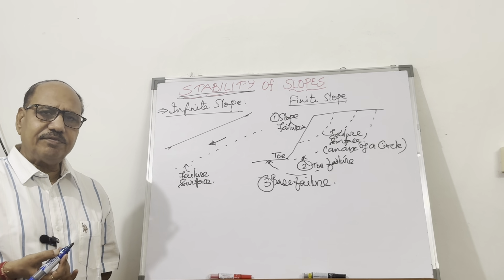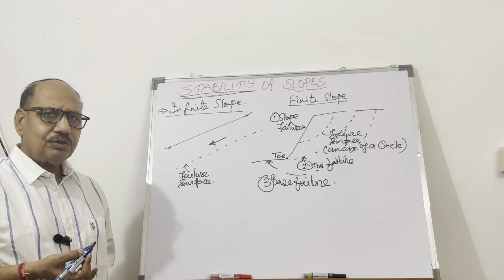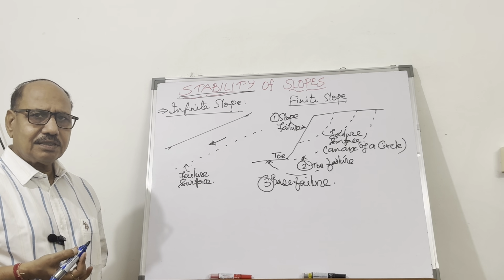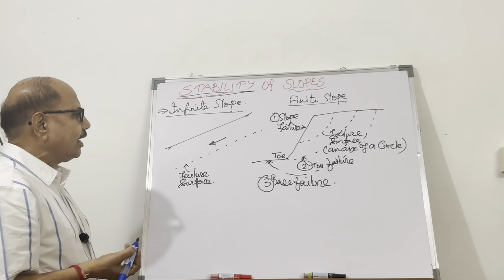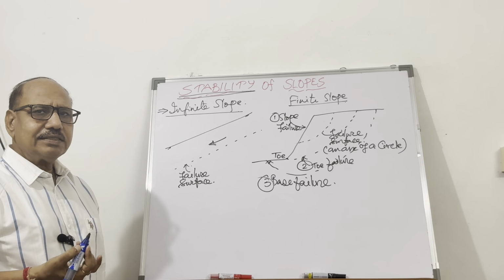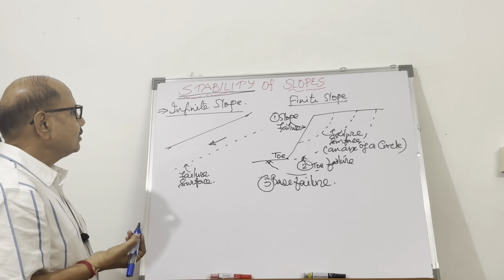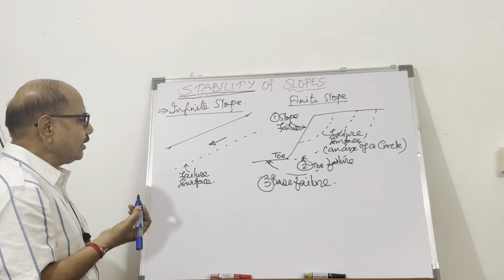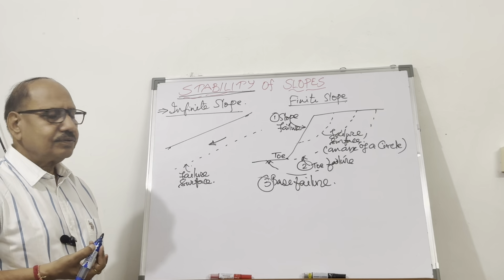Though that can be prevented, you can check the failure surface by reconnaissance survey or by aerial survey. You can find out, and you can take the remedial measures.